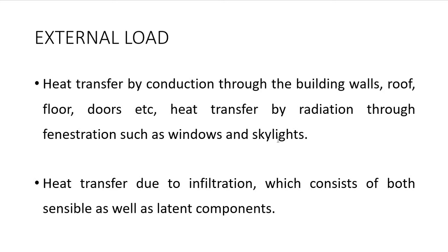So the outside air is at a higher temperature. When it is entering into the room, that temperature has to be removed or reduced. So that is an external load. Then the outside air has high moisture content. So when that outside air enters our room due to infiltration, the moisture content of our room air will increase. That also has to be removed. So heat transfer due to infiltration consists of both sensible as well as latent components.